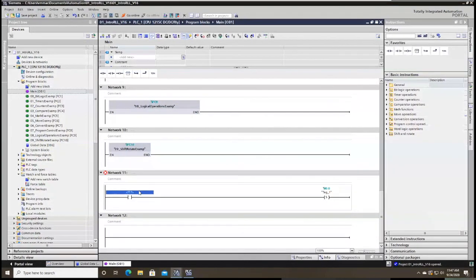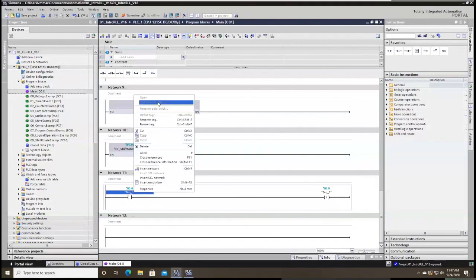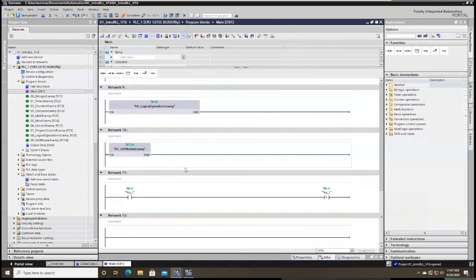I think that's one way of doing it. If you want to just replace those I's with memory tags in the meantime, you could do that. But I think you can also manipulate the program to set an input true, because I know it won't let you do this, for example. I can't add input 0.0 and do the modify like I would if I were online with a memory tag.